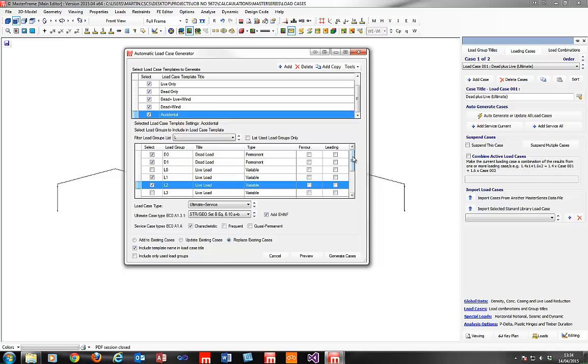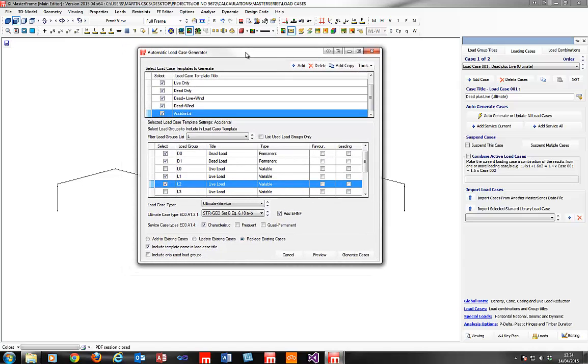In fact, we haven't really visited how we specify lots of different things. I don't have an option or a facility here to show you Eurocode 0, but simply in Eurocode 0 there are lots of psi factors against different types of variable load, and whether the load is for office use or for storage use, and particularly for the frequent and the quasi-permanent cases, those vary quite a lot between the different categories of load.